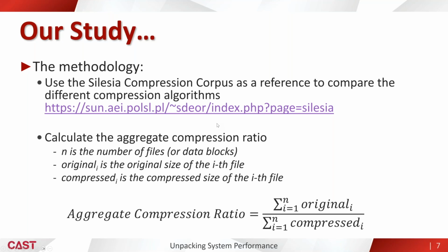And we used all these algorithms we discussed before to calculate the aggregate compression ratio. Mark this difference, please, because we don't use the average compression ratio, which is basically the compression ratio of all files divided by the number of files, but the aggregate one, which also takes into consideration the file size. This is much more helpful when we discuss throughput and performance of embedded systems, because the file size will impact severely the throughput of your file system, of your final system.